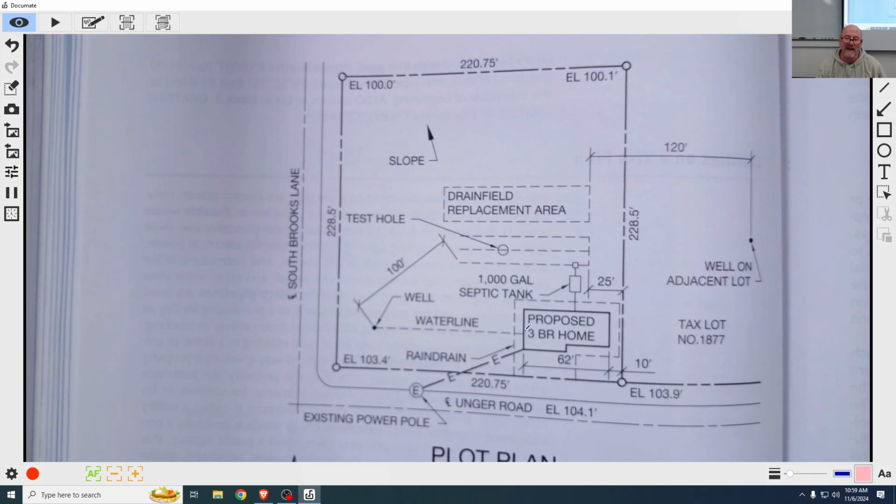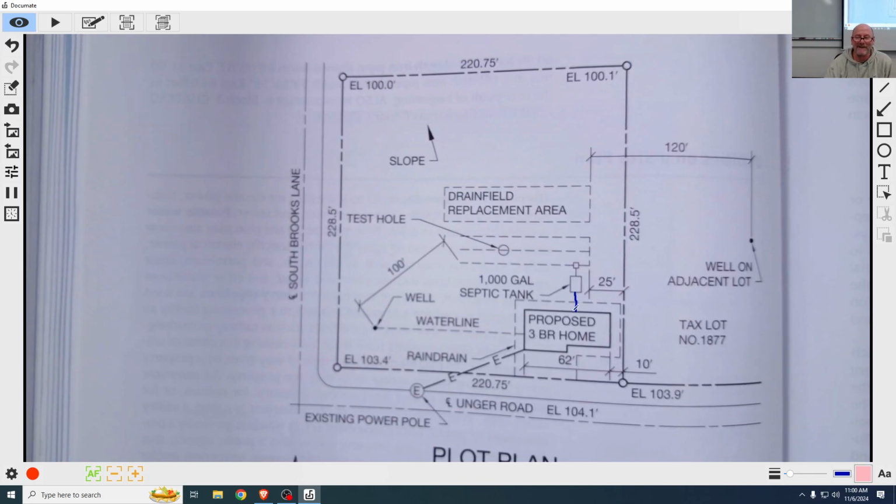So here's a house, has an electrical connection to it, has probably some water in here, has a drain going on for the rain. Now, over here, you have a drainage pipe coming out of the house. Usually, it's going to be listed as like a 4-inch or a 6-inch PVC or terracotta, like clay. Sometimes they're iron. Those things rust and go away, right? It's a good idea to know what you have, so you know what's going to happen.